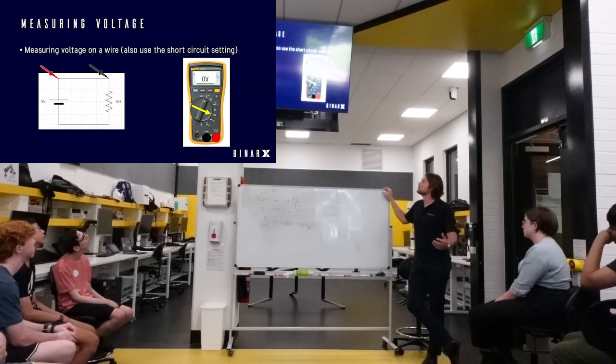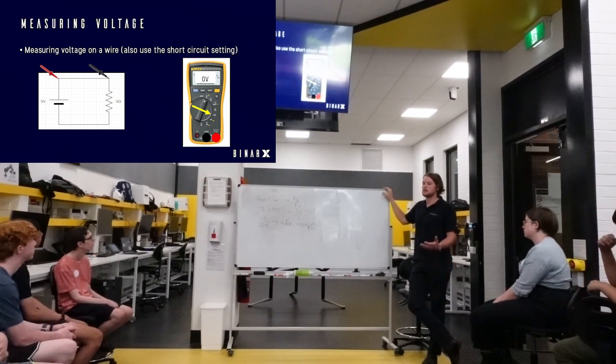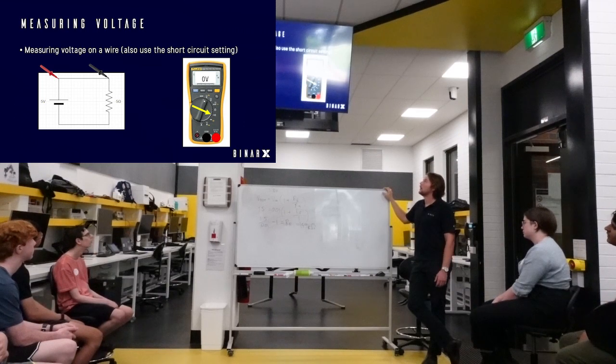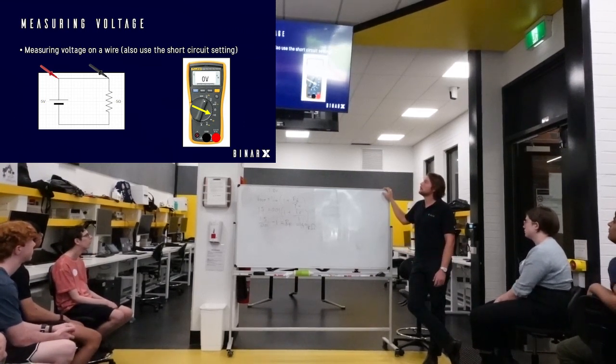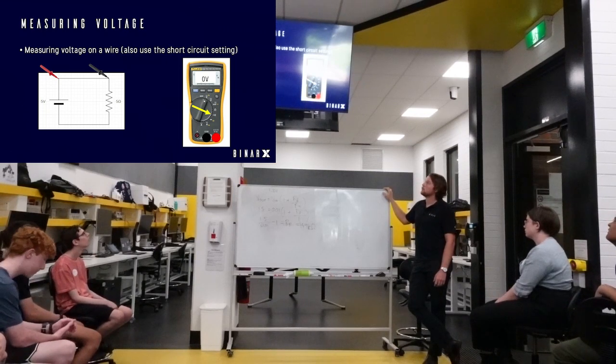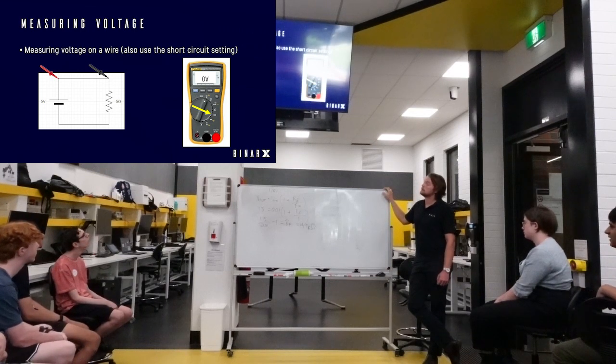Okay, so this time I'm trying to measure a short circuit, right? So is something touching something? This technically isn't a short circuit, but it's just trying to show the example of showing if something is touching, this is how you find it. So I've got it set to my beeping setting on the multimeter. What is the multimeter going to show here?